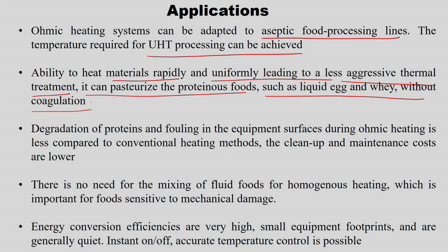Especially whey without coagulation, and degradation of proteins and fouling on the equipment surfaces is less during ohmic heating compared to the conventional heating method. Here, due to less degradation of protein, it will not form a layer near the electrode. If it forms a layer near the electrodes, there may be overheating near the electrodes.